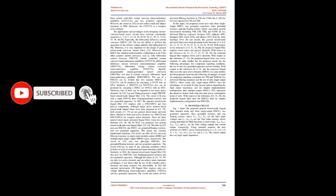Few general mixed-mode universal biquad filter structures employ 3 active elements of simple implementation configuration [6 to 8, 10, 22, 24]. For example, in [24], the reported general mixed-mode biquad uses 3 differential difference current conveyors, DDCCs, 2 floating resistors, 2 grounded resistors, and 2 grounded capacitors. However, it needs component matching conditions for realizing VM, CM, TAM, and TIM all-pass responses.